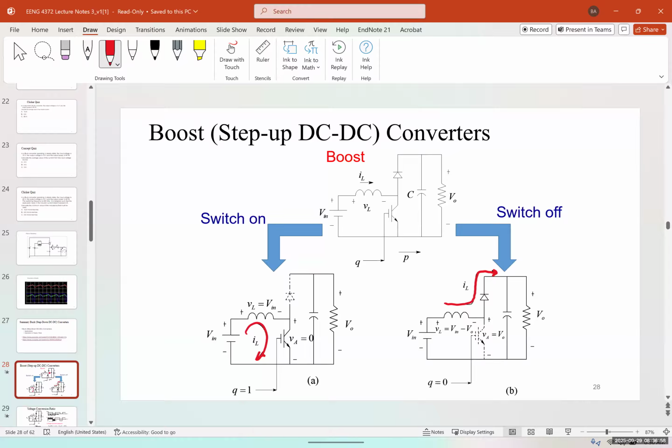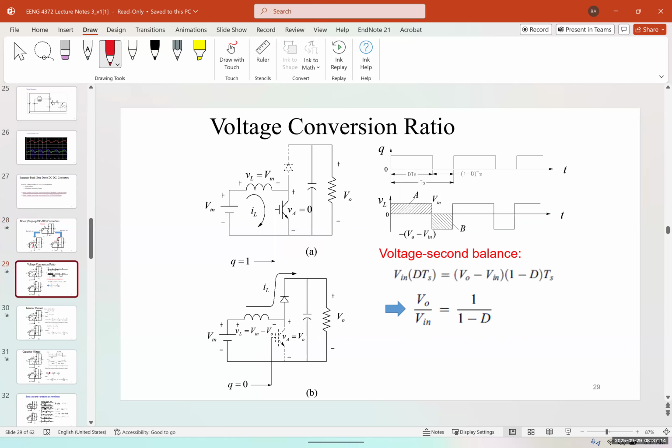For the inductor, it's the opposite. Initially it resists the increase of the current, therefore the voltage spikes, and then when it's fully charged, it acts like a closed circuit, the current is constant through it, and the voltage on it drops to 0.